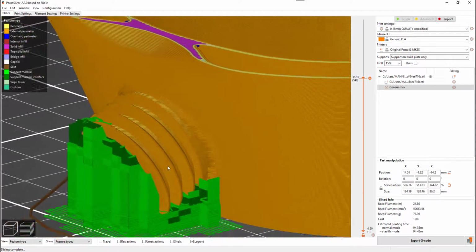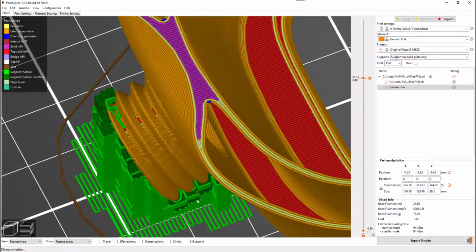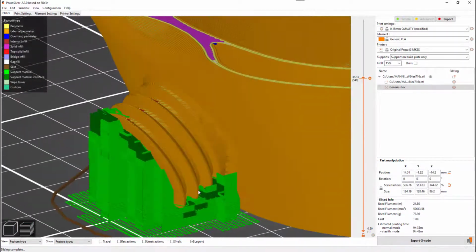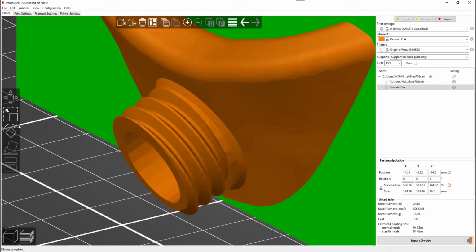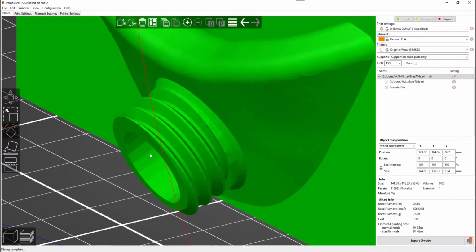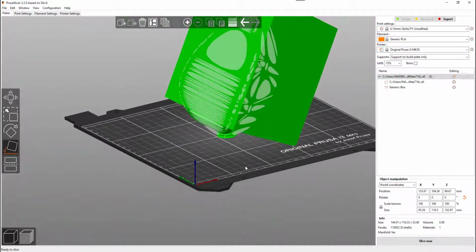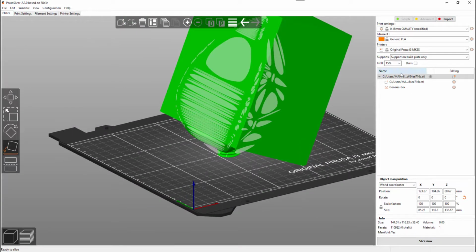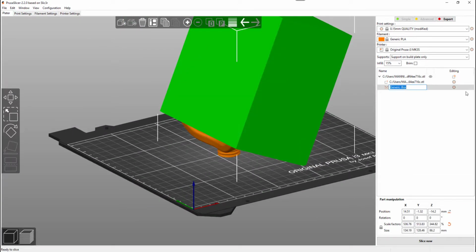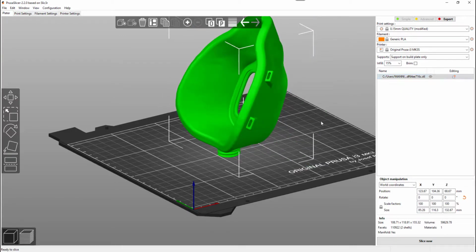You need to do a lot of cleanup. The original test didn't require much cleanup, and again, that's that offset we put in of 0.1 mil on each radius to give you that clearance and a little bit of flexibility. If you really wanted to, you could possibly orientate this, so you select that orientation onto that face, but there'd be a lot of, let's take that support blocker out too. Can I delete that?